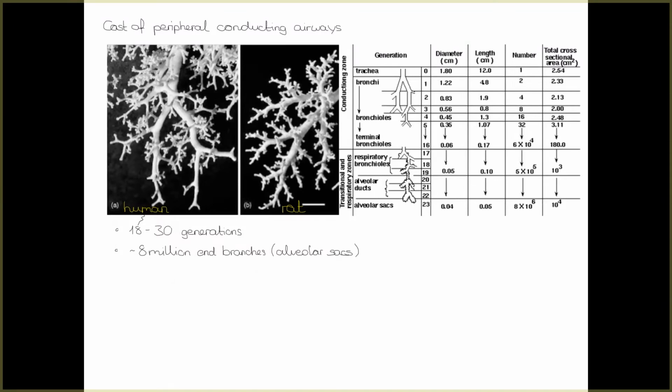We get the creeping flow, that's Stokes flow. That's what happens then even further down in the lung. So at the highest generations, the inertia term doesn't matter at all anymore. Okay, but important for us, very soon we get to a Reynolds number about that generation 5, which is small enough that we can say this is really laminar flow.